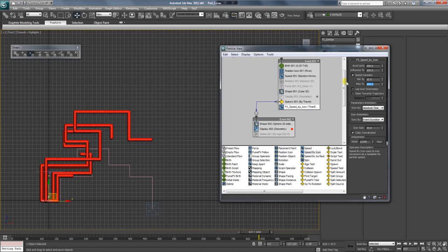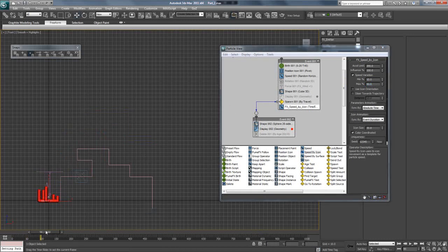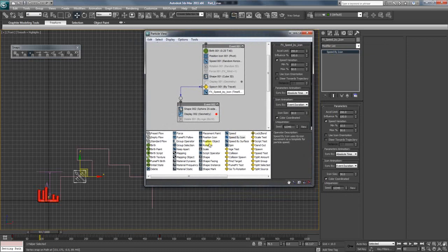We're going to have these things go across the screen. So I'm going to change the max value from 100 to 50 and see how the effect looks. There you go. Alright, continuing, playing the timeline, just seeing how the particles react. Again, changing the variation of the speed, having some start early, some not. Depending on the min and max, you can see how the behavior is, and some will get to the end point of that path earlier than others.